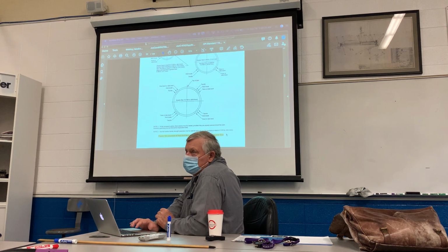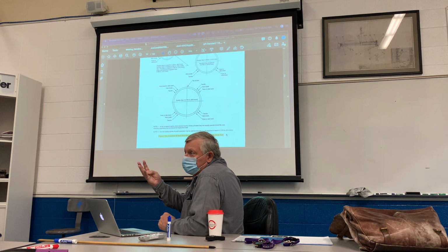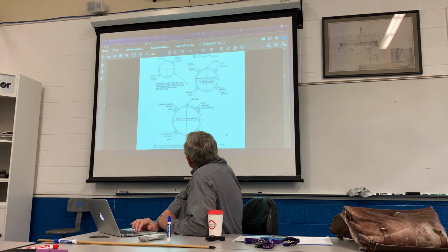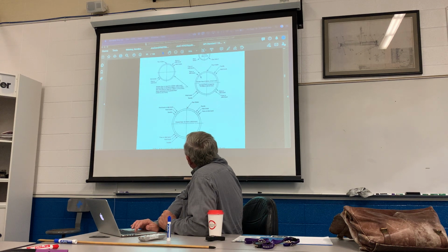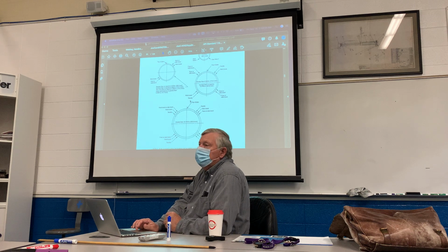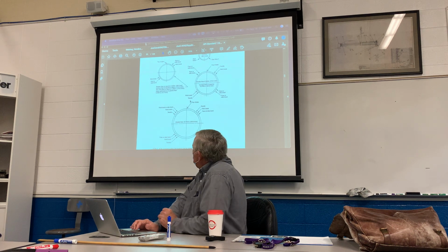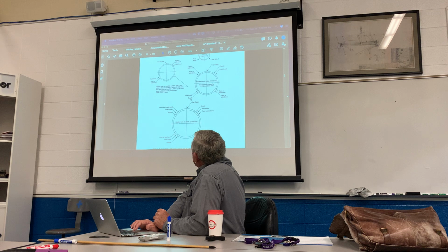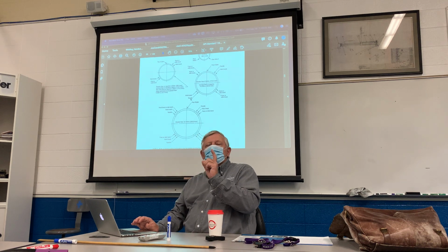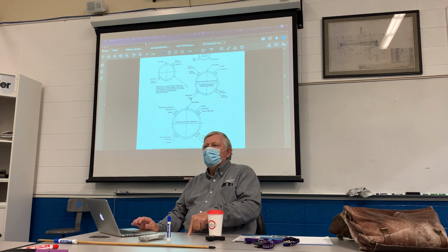This is a common mistake that happens all the time. You're testing welders and you'll find an inspector that's making them pull 4 straps. And notice that for 12-inch pipe, you're only pulling 2 faces, 2 roots, and 4 nicks. Now notice it says nick and tensile, and we'll look at that. But if you read down in the documentation, it says at the company's decision, you can substitute the tensiles for nick breaks.